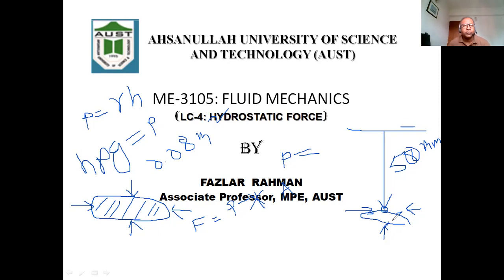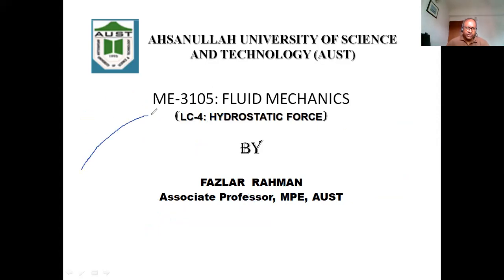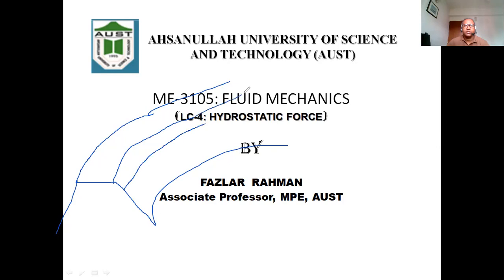So my intention is to explain the importance of the equation P equal to H rho G. The other thing is that fluid pressure is very important. If you do not calculate fluid pressure properly, you cannot design some structure which will be submerged in the water or floating in the water. For example, you cannot design a dam. Say you have a dam and this side has water. So if you design that the maximum water level in the front side will be this much height, then you see